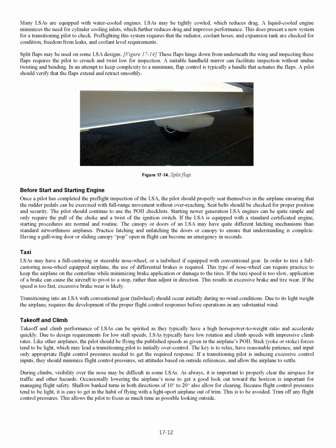Because flight control pressures tend to be light, it is easy to get in the habit of flying a light sport airplane out of trim. This is to be avoided. Trim off any flight control pressures. This allows the pilot to focus as much time as possible looking outside.